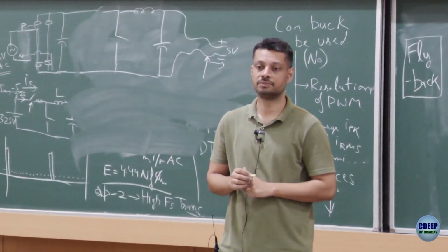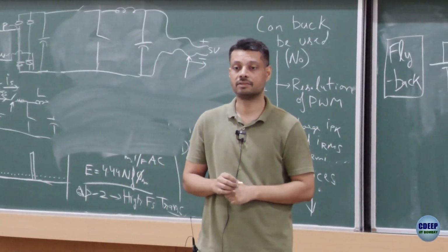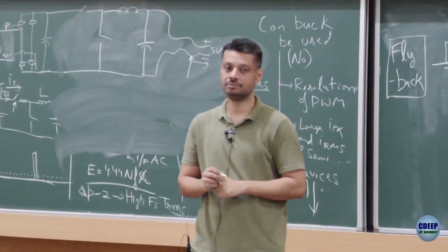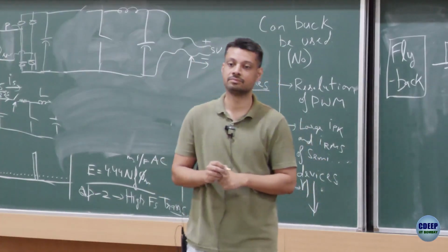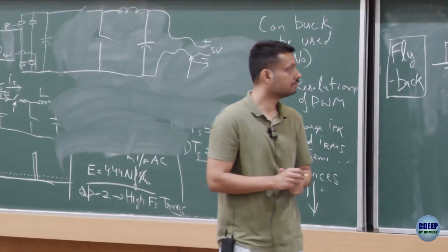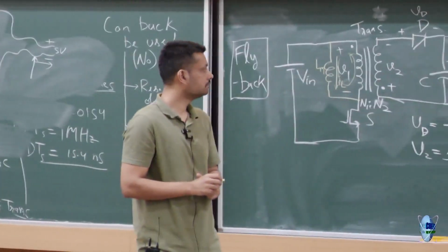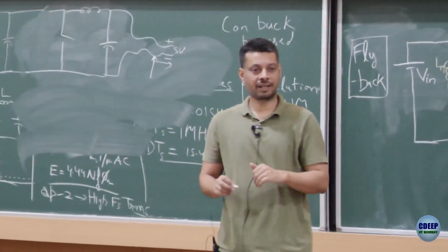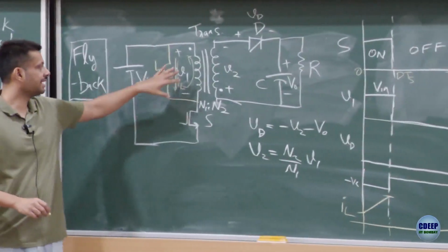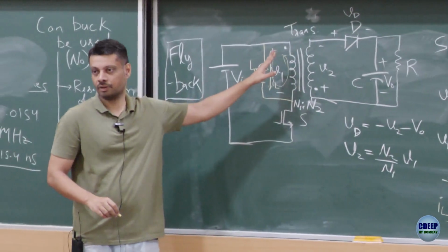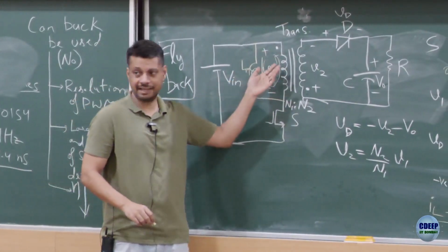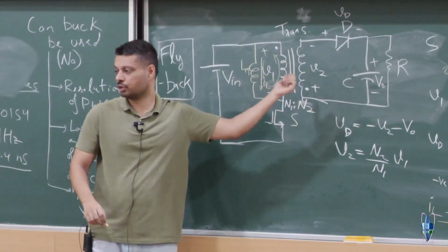On the left side the current is flowing straight out of the dot. So on the right side of the transformer, the current will be flowing into the dot. So the voltage across the resistor will be positive. So V2 is negative. Okay, so I think that's a good progress. What he's saying is current has to continue to flow in the inductor. So current will leave the dot. In an ideal transformer, on the other side, current would enter the dot, right?